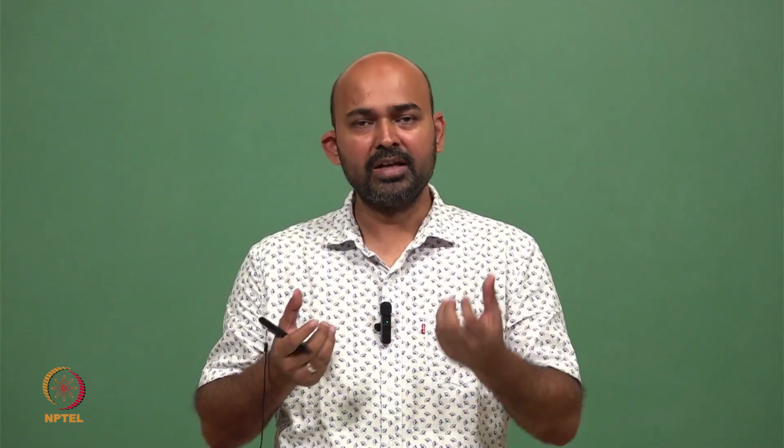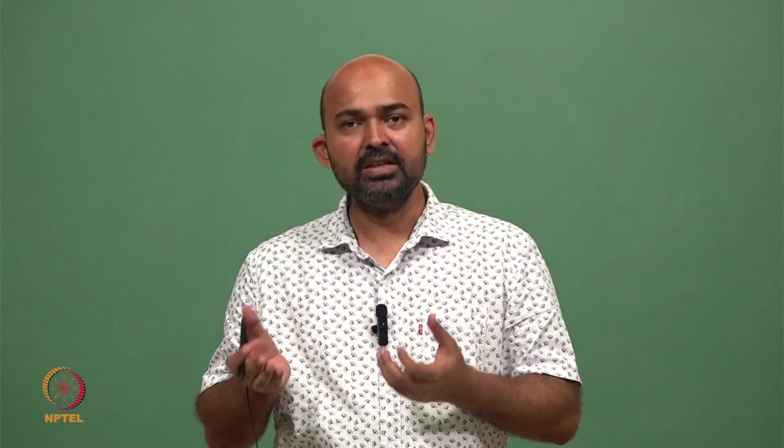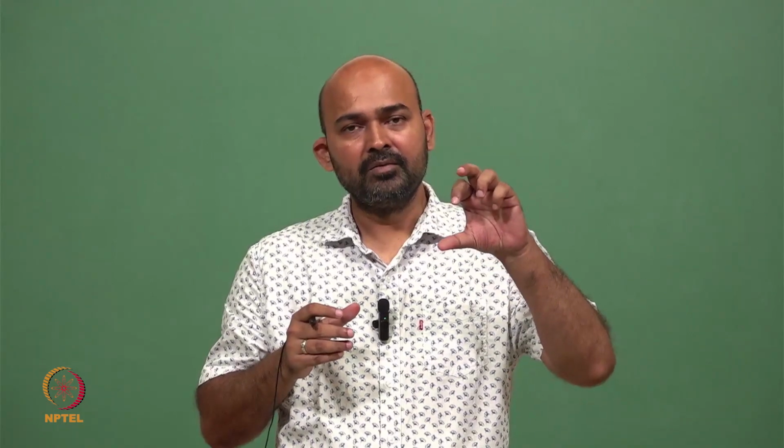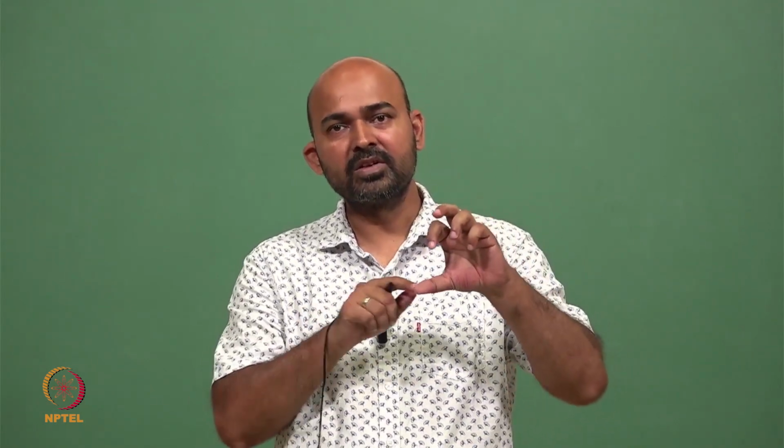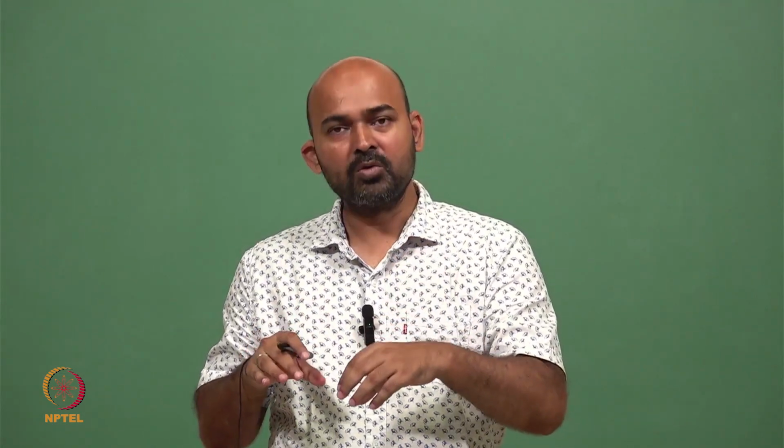and to measure a threshold voltage shift in a MOSFET, either we can use the IV characteristic, the current versus voltage characteristic, or we can do a CV characteristic where we plot the gate capacitance versus the applied voltage. This CV characteristic, the capacitance voltage characteristic, shows the shift in the negative gate voltages, and this shift is proportional to how much the threshold voltage changes. So this shift is proportional to the amount of radiation detected by the MOSFET.